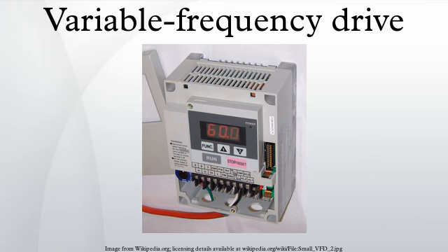However, motor cooling deteriorates and can result in overheating as speed decreases, such that prolonged low-speed motor operation with significant torque is not usually possible without separately motorized fan ventilation.